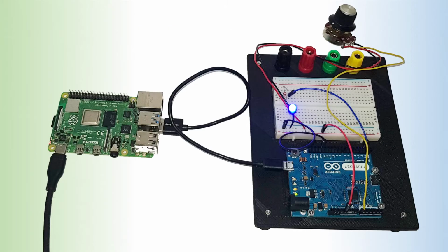This is the setup I've got here, which is just to demonstrate the Raspberry Pi and Arduino communications. There is an Arduino, which has an analog input. In this case, I'm using a variable resistor. This could be any kind of analog input, such as a light sensor using a light-dependent resistor. There is then a digital output, which in this case just lights up a blue LED. Again, this is just a simple demonstration, so you could use these to drive servo motors, control hundreds of NeoPixels, or just about any other kind of electronics.